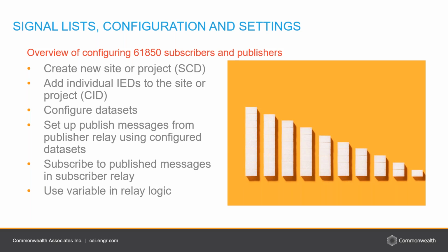So typically the process is you create a new site or a new project. Costa was talking about the hierarchy of the SCL files, and that's SC as in Charlie, L files. So the site or project is typically called SCD, so even the file extension is SCD. And within that SCD, you have your individual IEDs that you add to that site or project.